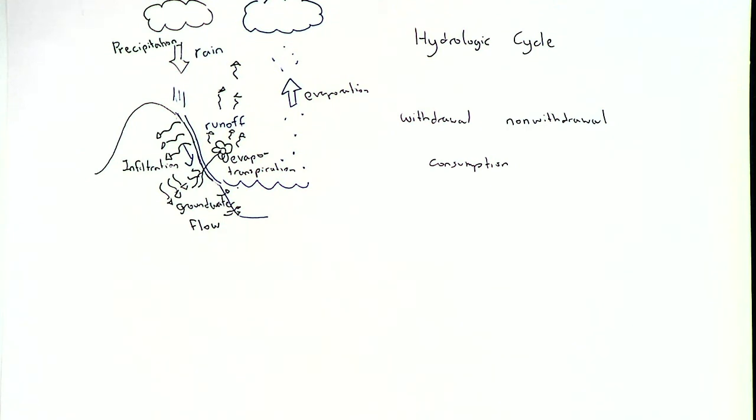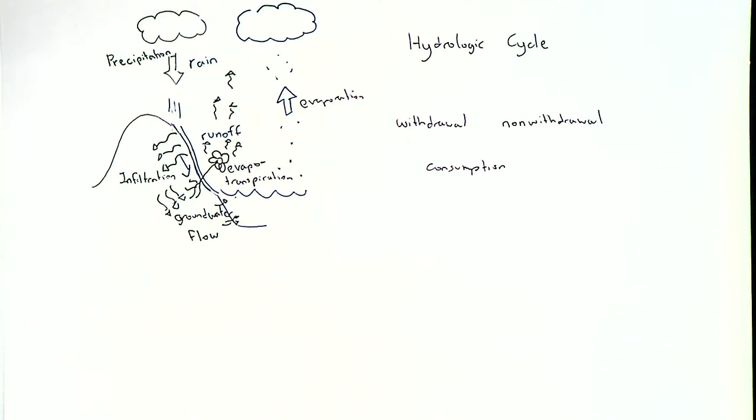We can divide municipal water into domestic use, public use, commercial use. I really don't want to just give you a list of things because you can read those from the book. What I want you to understand is that typically this water will receive the highest priority. Even though we use it for recreation, for cleaning and for hygiene, we also use it for drinking. And because it's all the same system, it should receive the same priority as our drinking water. It is simple to determine how much water we need, but normally we can't determine that perfectly, so we typically want to go a little bit above that.